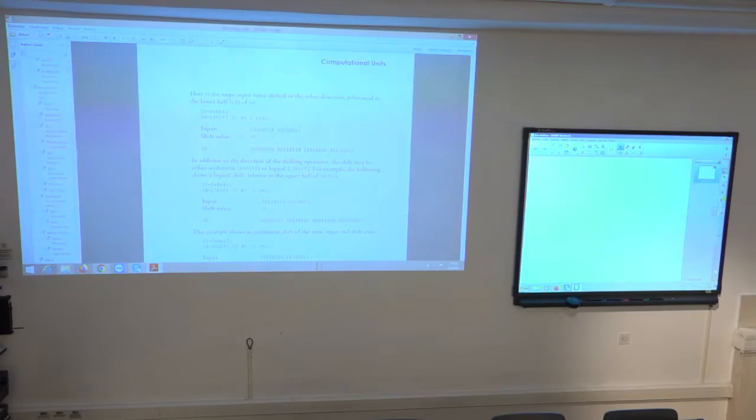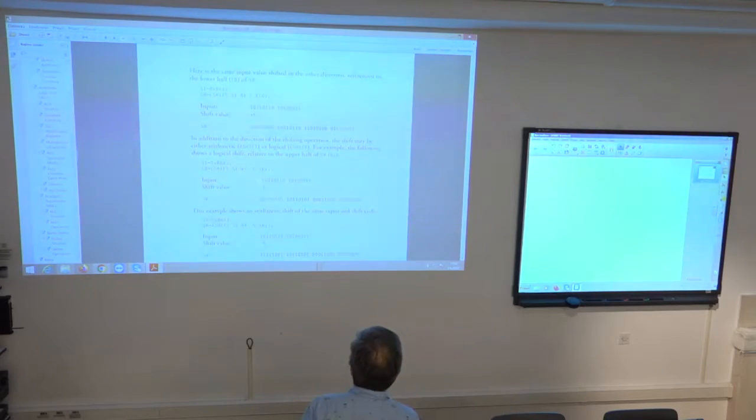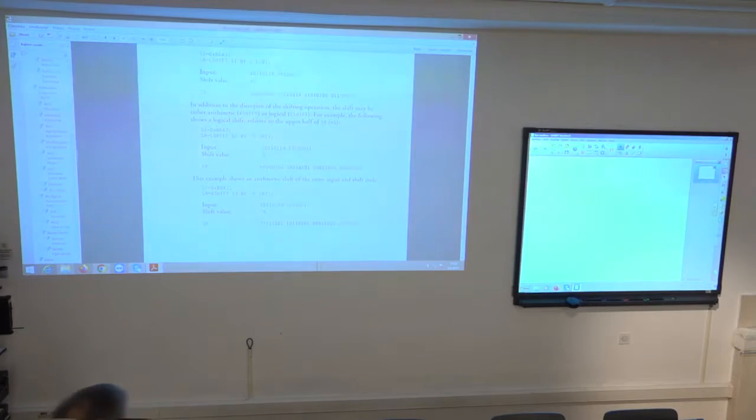And the difference between the logical shift and arithmetic shift is exactly in handling the sign bit, because the next example shows the arithmetic shift. Arithmetic shift, again, by 5 positions relatively high. Since the input value is negative, the most significant bit is set to 1. Then this sign bit is repeated 5 times: 1, 2, 3, 4, 5. And then I have this 1, 0, 1, 1, and so on. So the arithmetic shift keeps the sign of the input value as desired.